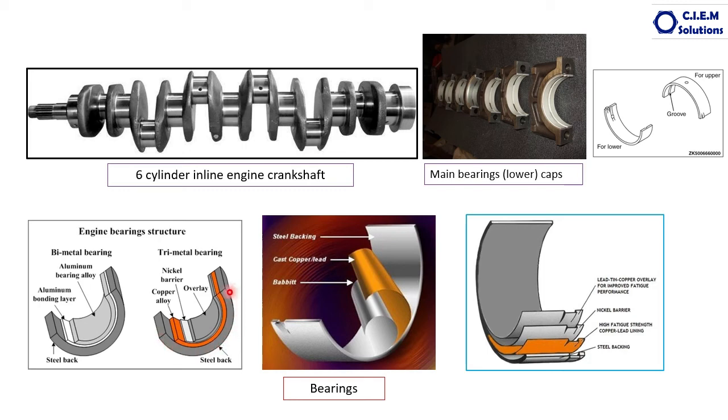It should have the required tension to stick onto the bearing housing, cap or bearing housing always. It should have the grip there, and it should also give strength to the bearing. This is why it is a steel back. The middle layer is copper alloy.